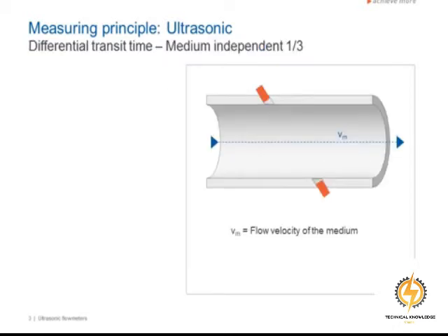In order to understand the technical background, but without going too deeply into the construction of an ultrasonic flow meter, we can look at the most important features. The transducers, which are always in pairs and mounted under an angle, consist of a transmitting and a receiving transducer, which we can call transducer A and transducer B. The two transducers act both as signal transmitter and signal receiver.